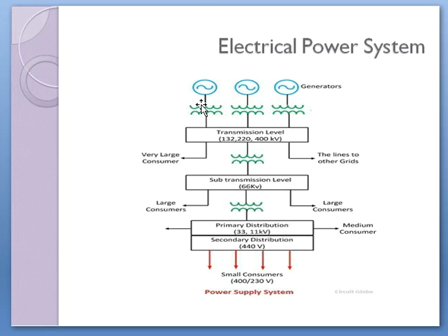Ultimately, the output from the switch yard is connected to the transmission line towers through 3 bus bars, and thus the voltage that is generated in the stator of a thermal power plant is now transmitted to the external transmission line system.